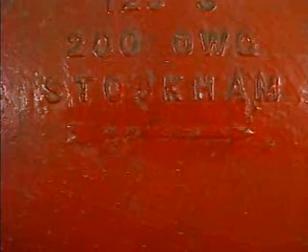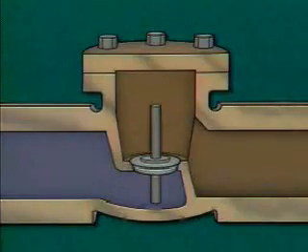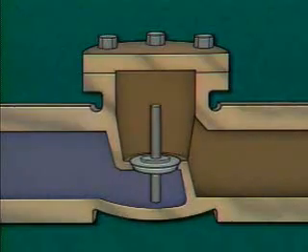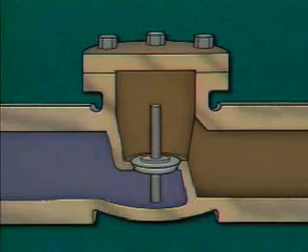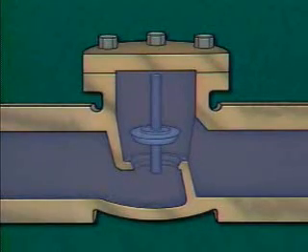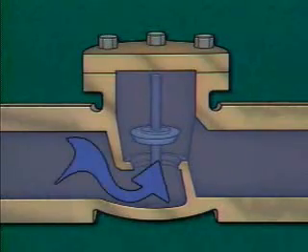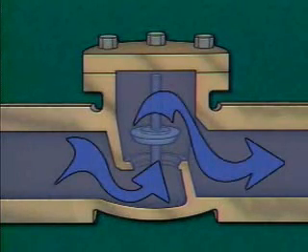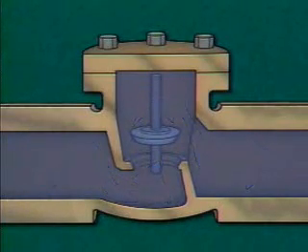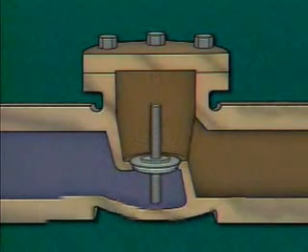the valve body. As with any type of check valve, the disc in a horizontal lift check valve is positioned so that fluid will flow under the disc. When fluid enters the valve body and system pressure is greater than the weight of the disc, the disc is lifted off the seat. Fluid flows through the valve, then on through the outlet. When system pressure is reduced or flow is reversed, the disc moves down onto the seat.